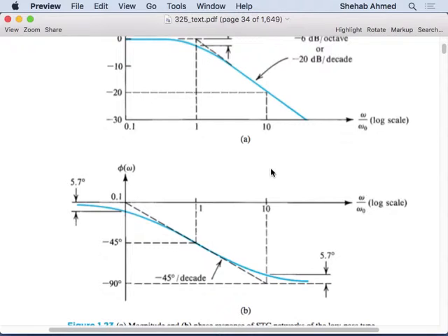So really, is somebody going to recognize, okay, Aziz is singing, and that there's a delay in the output from the speaker? Not really. But if it's data on the internet or image data that you're transmitting, and there's a delay, you may be able to recognize that. There are things that you cannot recognize, like audio speaking, unless the delay is very long. There may be things that are very critical, like power system fault analysis, when you want to make sure that all the samples are exactly synchronized. Because if you don't, maybe the circuit breaker opened before that one, but because you have delays and phase shifts, you don't really know what's happening, right?